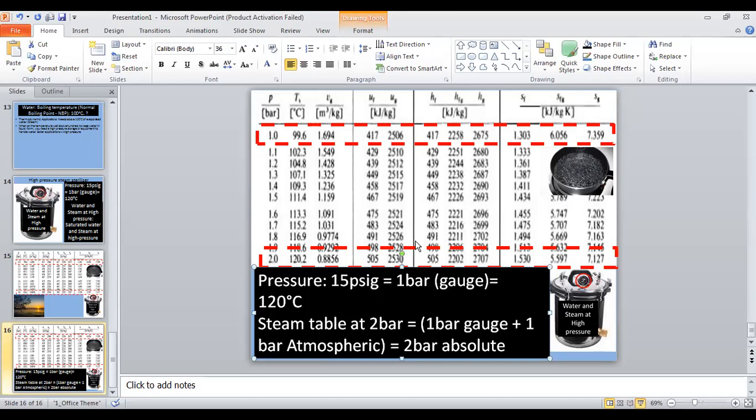Again, the thermodynamic system. And 2 phases, we came to liquid and vapor. And understanding of normal boiling points, we have done it to the fullest. So we know how the gaseous form substances at normal conditions. To keep it in bigger masses, you have to put it under liquid form. So you need to apply very high pressure on that. So that's why R290 like applications need high pressures.